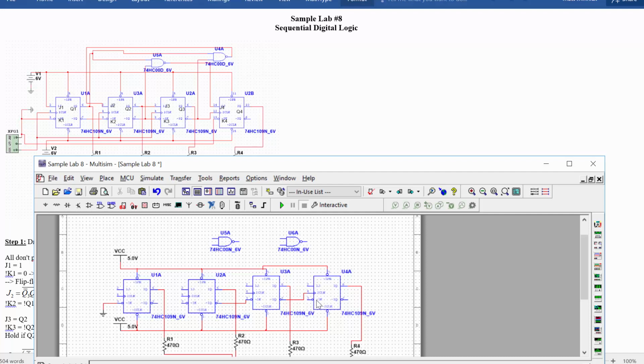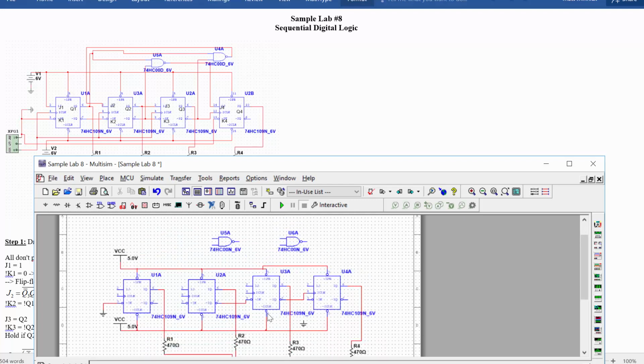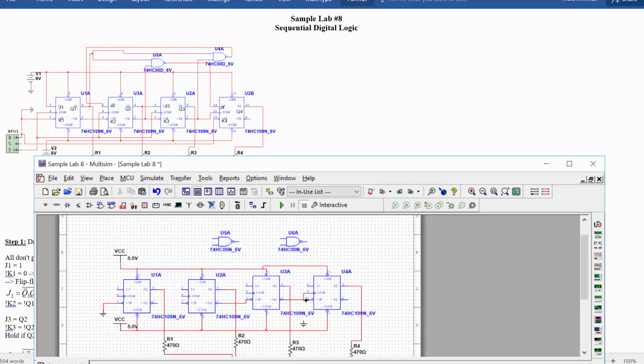I find it easier typically to think in terms of inputs. So we'll check that all the inputs work on all the different things. And as long as everything has the input from the right thing, then everything must be all hooked up correctly. So this K is connected to ground. So we don't need to wire that all the way across like we have in the diagram. We can just make a new ground symbol here. It's going to be a little bit less clutter to do it that way. Then we've got the J4 here goes to that NAND gate.